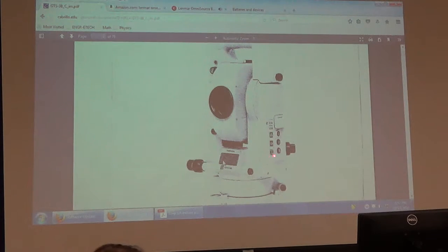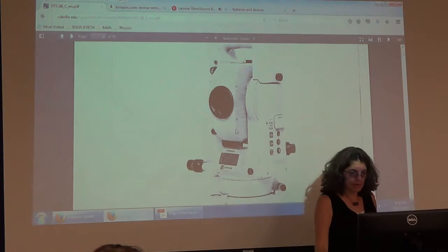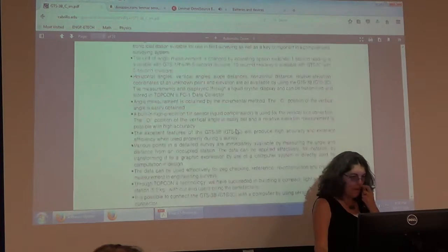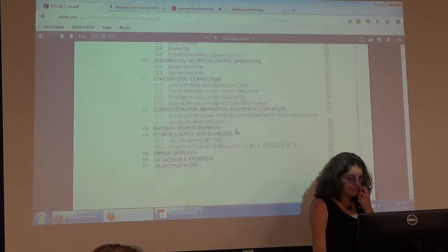I don't know if you could read this. It says V/H. What do you think the V and the H should represent? Vertical and horizontal, and it's not distance, it's angle. This one is angle, so it's a vertical angle or a horizontal angle. So depending on what's pressed, it'll show you what the vertical or the horizontal angle is. Okay. And then there are buttons on the other side. Can we turn it around? Yeah. Let's see.